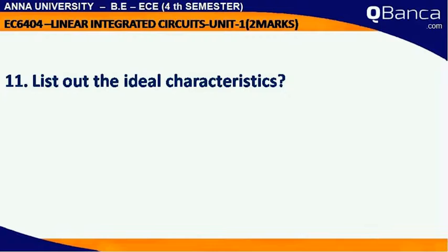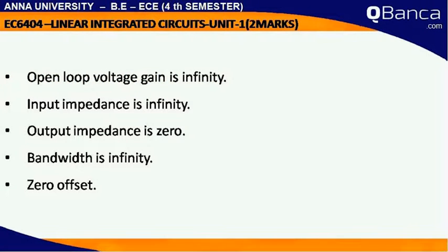Ideal characteristics. Open loop voltage gain is infinity, input impedance is infinity, output impedance is 0, bandwidth is infinity, 0 offset.